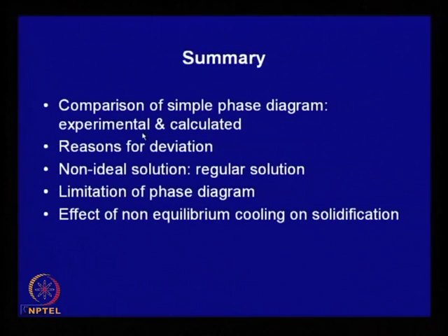To sum up, today we looked at a comparison of simple phase diagrams, which are calculated theoretically from a simple model, and experimental diagrams. There are some deviations. We learnt about why there is a deviation. We went a little higher order of calculation using the regular solution model, which will give a better fit. Then we looked at the limitation of phase diagrams and also looked at the effect of non-equilibrium cooling on solidification. Thank you.